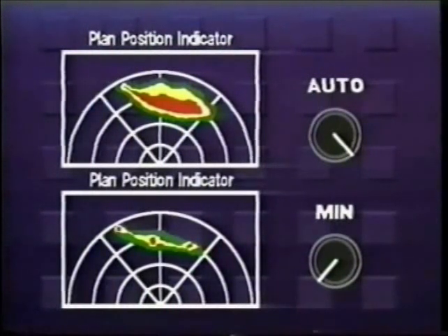The manual gain control is used to adjust the sensitivity of the radar's receiver. One application is to reduce the signal strength of strong target echoes so that they may be resolved on the display. By doing so, it becomes possible to determine the relative intensity differences between strong thunderstorms. As the gain control is rotated counterclockwise, the receiver's sensitivity is decreased. Manual gain must be left in the auto position to use the radar in a calibrated weather mode.